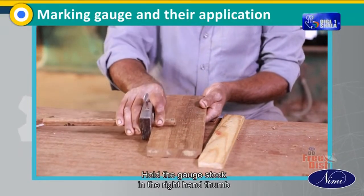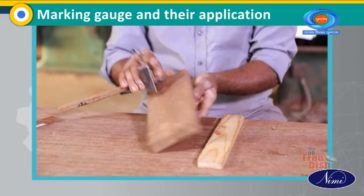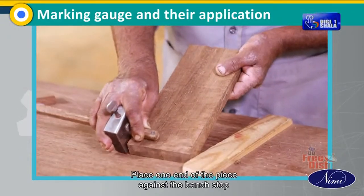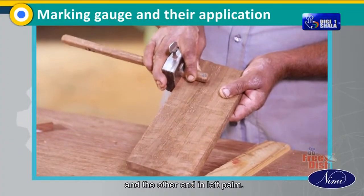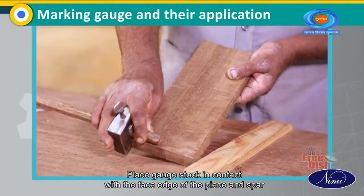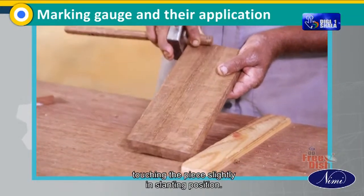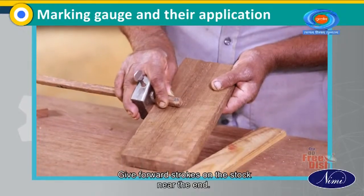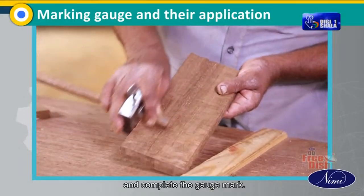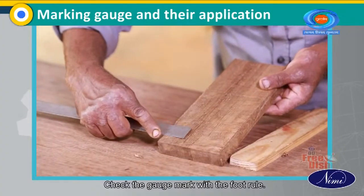Hold the gauge stock in the right hand, thumb on the top behind the spur, the forefinger on the stock and the other three fingers on the stem of the tool. Place one end of the piece against the bench stop and the other end in the left palm. Place gauge stock in contact with the face edge of the piece and spur touching the piece slightly in slanting position. Give forward strokes on the stock near the end. Hold the piece in your left hand and complete the gauge mark. Check the gauge mark with the foot rule.